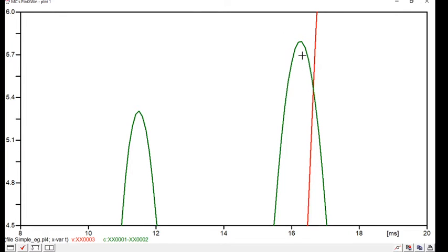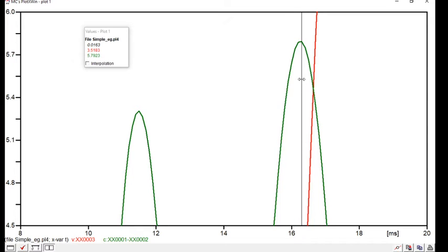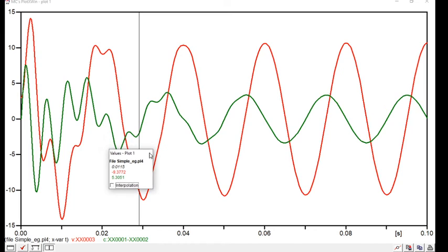If you want to note the value, this tool helps you out. If you click down here, there is a button like a marker. You get this line, and you can measure each and every voltage. You can note the time here and the time here, take the difference and invert it, and you will get the approximate frequency of the mode for this setting.